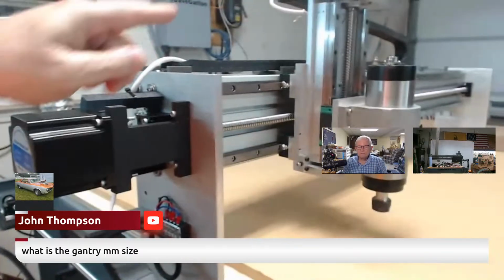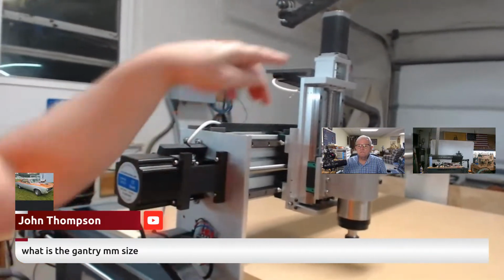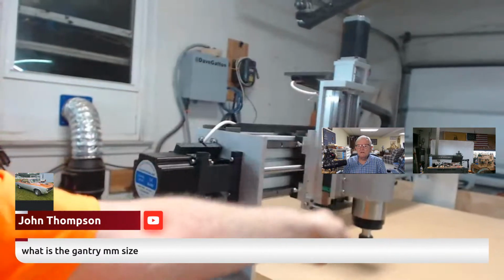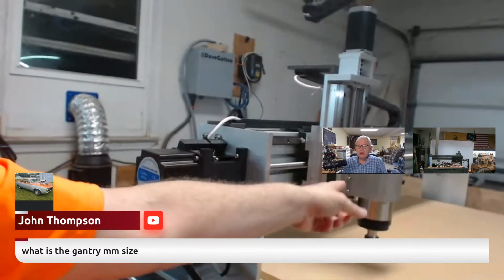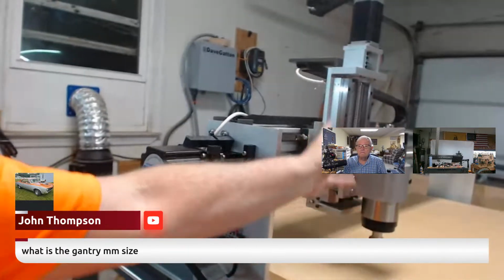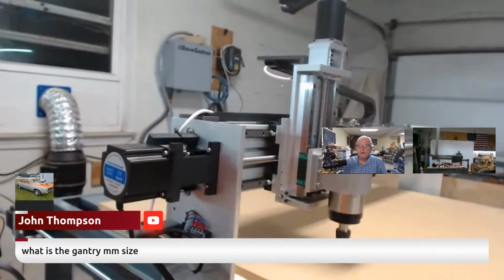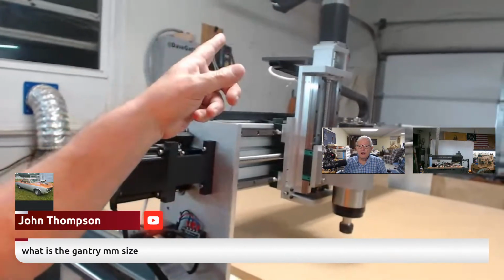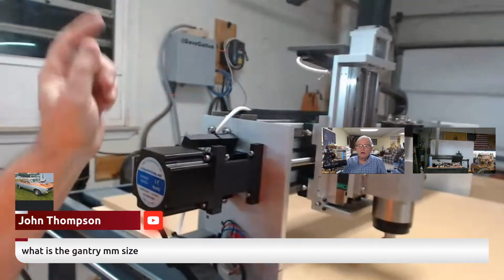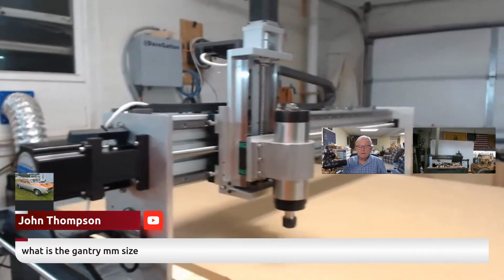That one up there, because I'll try to lean back here and get that one. That one up there, because it's a NEMA 23 and it's holding up a lot of stuff right there. That spindle is about 20 pounds by itself. And then you add all that other stuff, on a ball screw trying to hold it up. I left it on full current. And when I checked that sucker, it got to about 150 degrees Fahrenheit. So it gets way hotter than these other three.